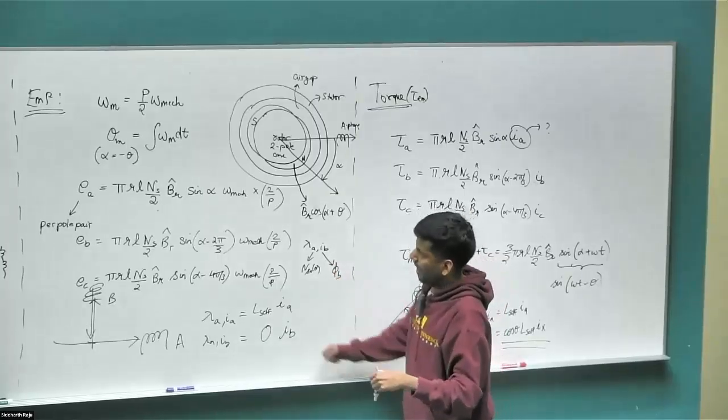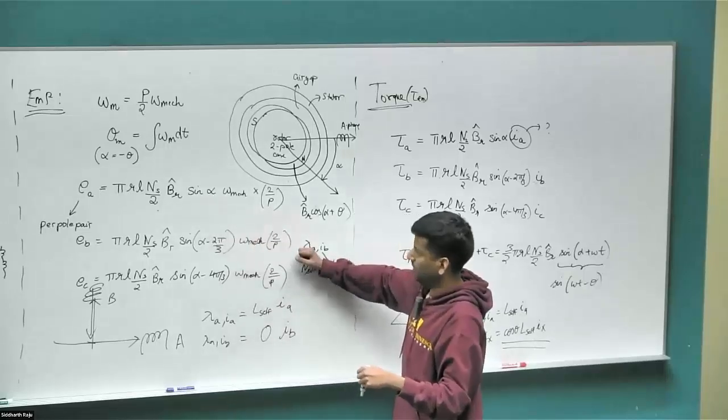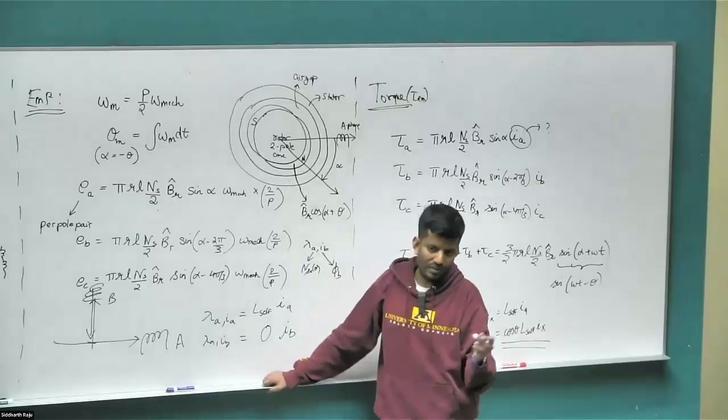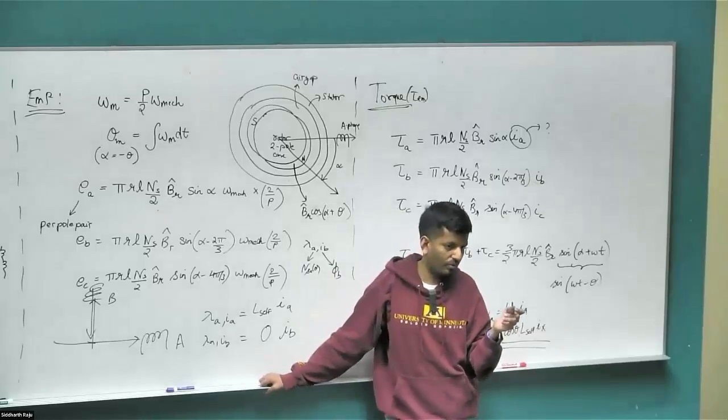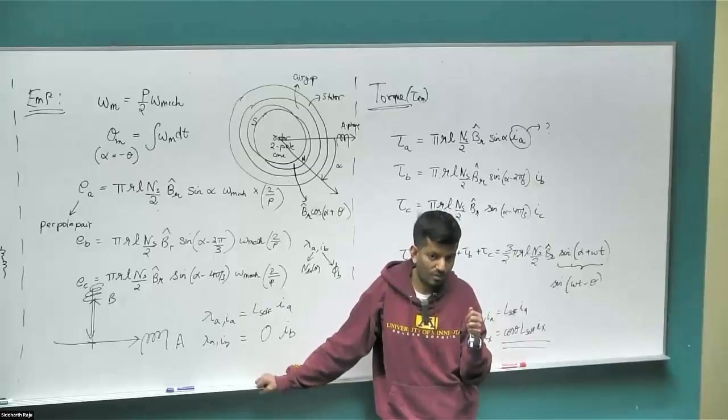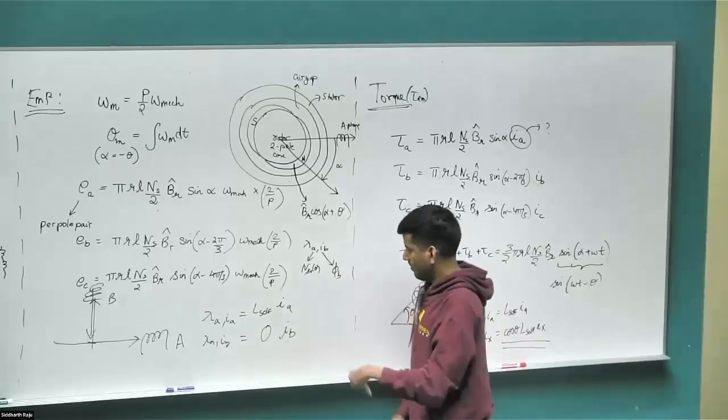And then we used the flux coming from the B phase coil. Now, for the back EMF, we are going to do the same thing. We need to get the flux linkage first, and then once you have the flux linkage, how can you get the back EMF? Let's say I give you the flux linkage of the A phase coil. How do you figure out the back EMF of the A phase coil? What's the relationship between flux and EMF? Let's start there. Yeah, please. E equals N d phi dt. And d phi dt, perfect.